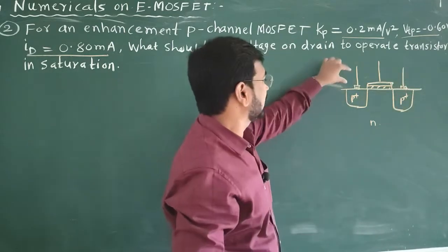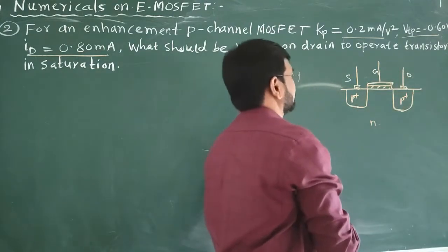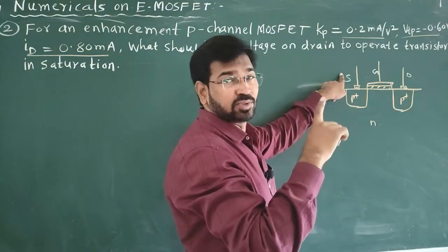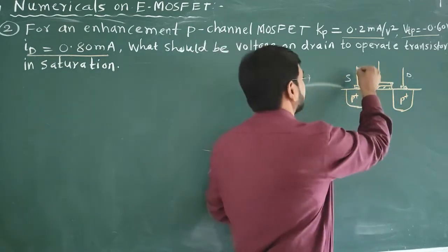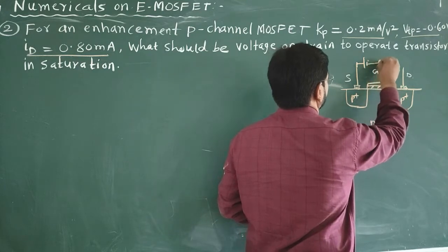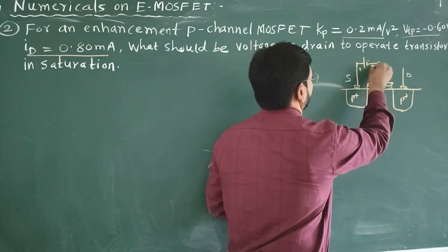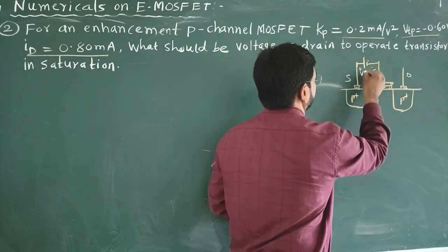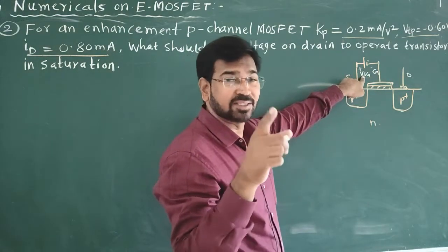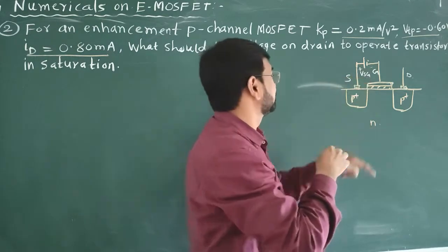Okay. The voltage on source and gate. So gate voltage is negative with respect to source. So source is at positive in PMOS. So it is plus and minus. We are keeping notation simple here. So this voltage is VSG. Okay, so S is before G. It means S is positive with respect to gate. That is the major difference between NMOS and PMOS.